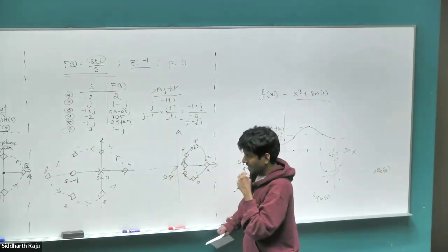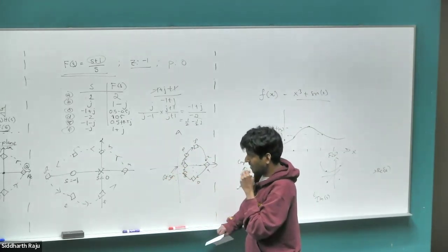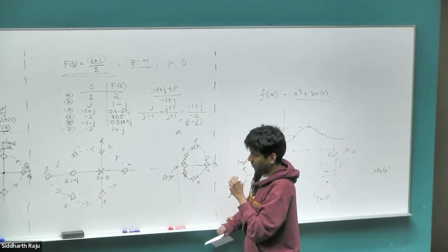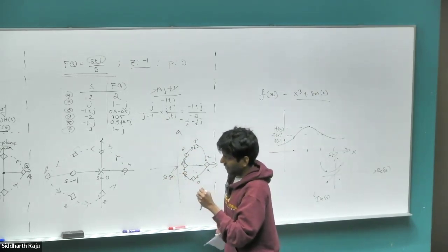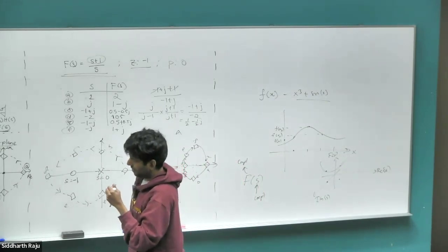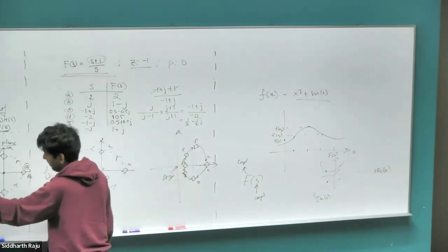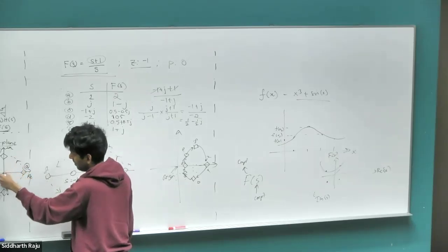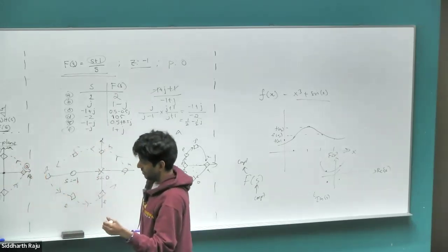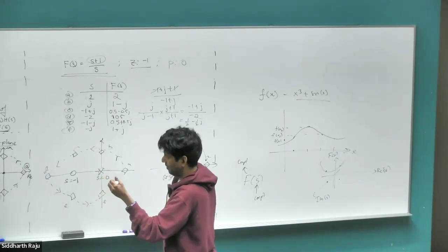Right, so we haven't done a sufficient number of examples yet to be able to make any kind of conclusion. But at least one thing that we can observe is the case where we had just a 0 and we encircled it with a loop. Then in the f of s plane, the loop encircled the origin in the anti-clockwise direction, same as the loop direction that we chose.